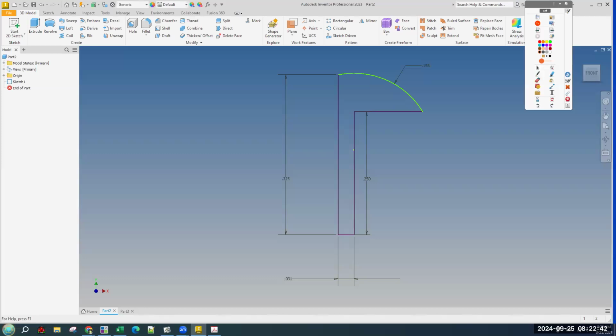Okay. Hit cancel. Right click on sketch one in your browser bar. Yeah, that. And right click and do edit sketch. Right click on the word sketch one. Right click. Edit sketch. It's like third or fourth at the top. Okay. And grab that endpoint.